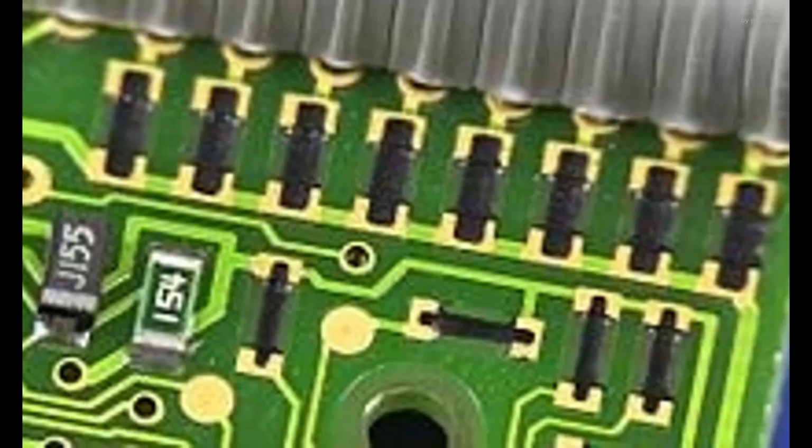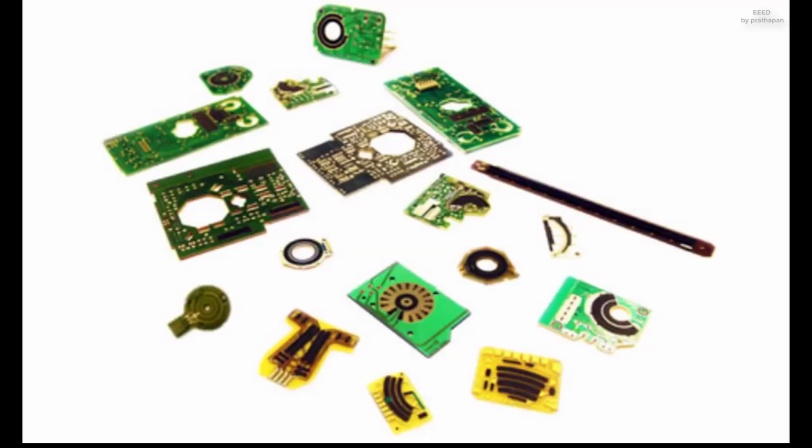Printed carbon resistor. A carbon resistor printed directly onto the SMD pads on a PCB. Inside a 1989 vintage Psion 2 organizer. Carbon composition resistors can be printed directly onto printed circuit board, PCB, substrates as part of the PCB manufacturing process. Although this technique is more common on hybrid PCB modules, it can also be used on standard fiberglass PCBs. Tolerances are typically quite large, and can be in the order of 30%. A typical application would be non-critical pull-up resistors.